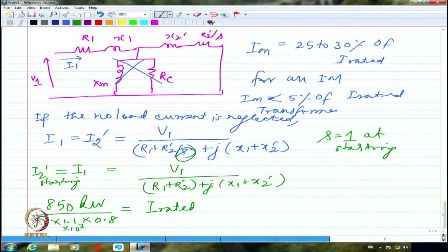This rule is there because induction motors take heavy starting current. You will see a dip in the voltage. Normally, with welding equipment connected directly to the supply, you will see all the lights going very low. The same thing you can observe if you are starting a very large capacity induction motor, because the voltage will really sink. It will become very low, normally for a short while until the machine gets started.